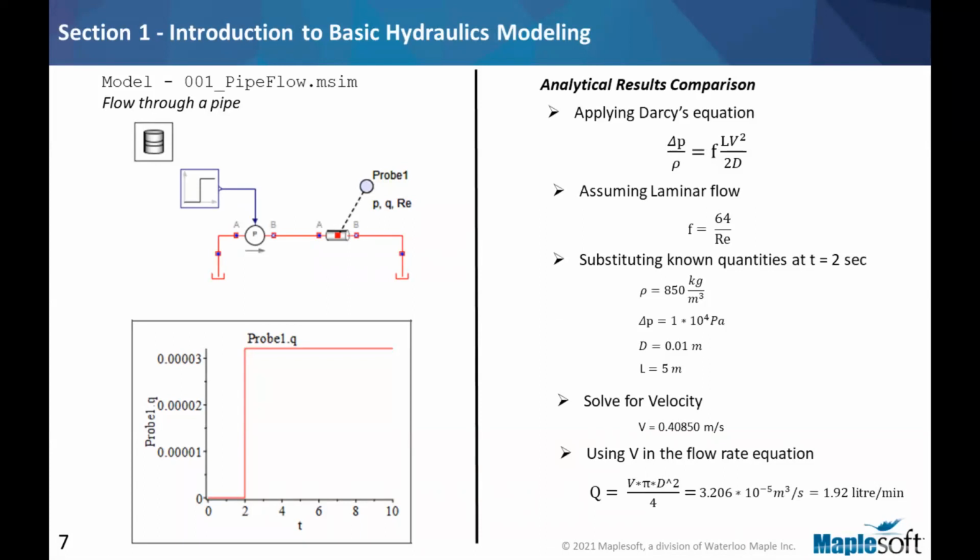Now here, like I'd mentioned, we've just used Bernoulli's equation inside the flow through the pipe. So this is the relationship for the pressure drop as a function of velocity by applying Darcy's friction factor here. Because we've assumed laminar flow, and the Reynolds number is, I think, around 200, and that is a laminar flow, the friction coefficient is given by the equation that I've defined. These are all general equations that we can find online that we would have studied in our first year of engineering.